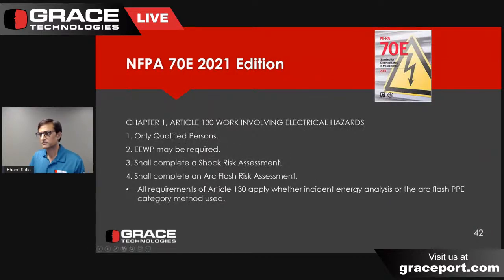So basically, I've been tracking some of the questions, and I just want to make sure that I answer a few as we go. Some comment came back about, well, can't we still use the 2012 or the 2015 version of 70E? No. As soon as a new version of 70E or Z462 is published, the previous editions are obsolete. So that's another problem. You need to keep current with your policies, practice, procedural requirements based on the latest edition. Once a new one publishes, the other one's obsolete, right? So you've got to move on and change.